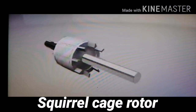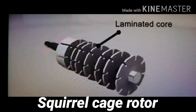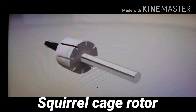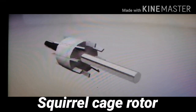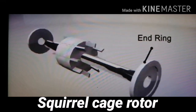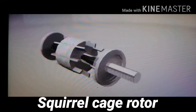It consists of a laminated cylindrical core having parallel slots on its outer periphery. One copper or aluminum bar is placed in each slot. All these bars are joined at each end by metallic rings called end rings.